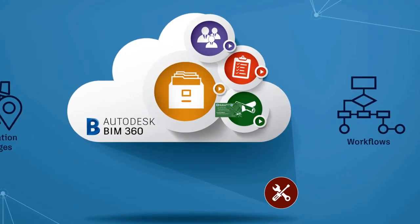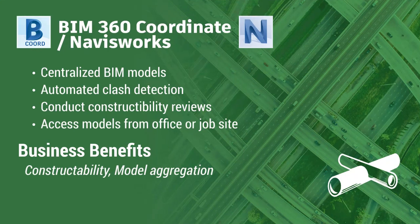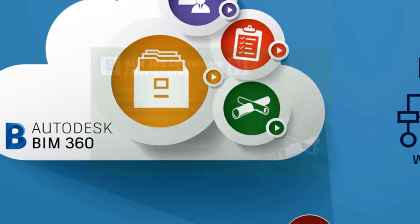And the last one we touched on was around BIM 360 Coordinate. We didn't use that in its truest sense, that we didn't use that module on the civil side. We kind of supplemented that functionality with Navisworks, and then using a plugin, we were able to create those issues so that we could aggregate model components together and then run some analysis or create a test so that we were able to report back those things that needed to be corrected. So the business benefits for that is going to be around constructability and model aggregation.